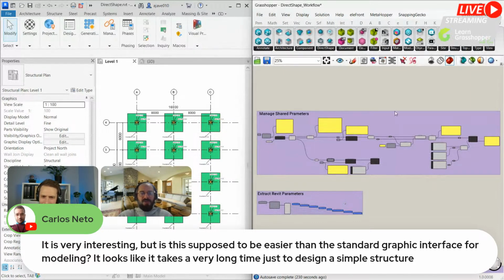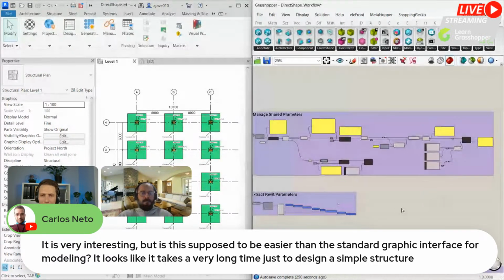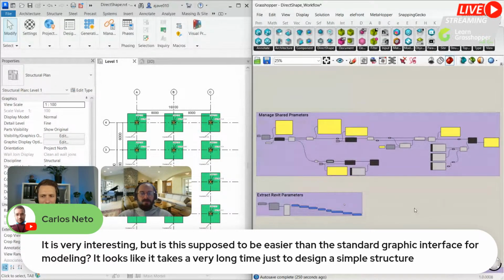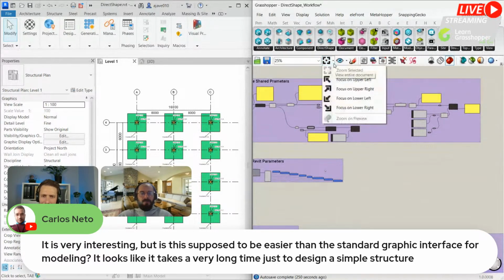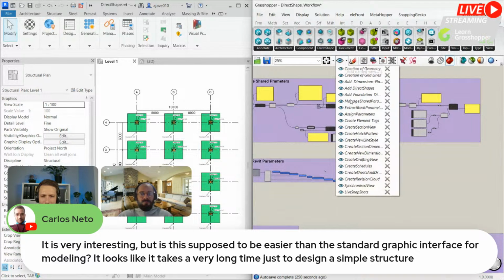So I was just opening up the project, I was running the script, and within 30 minutes, I remember that I filled all the parameters for 10 to 15 projects. So you don't have to make everything, all the parameters, defined in Grasshopper. You can use external tools like Excel, and through Grasshopper assign it to Revit.